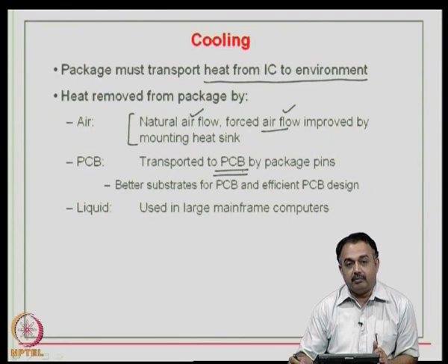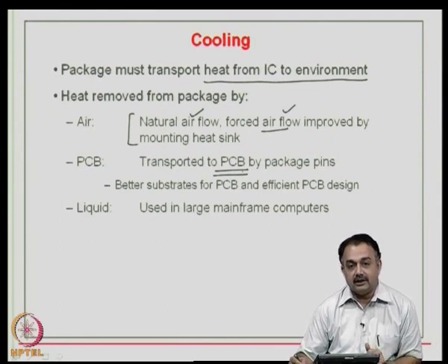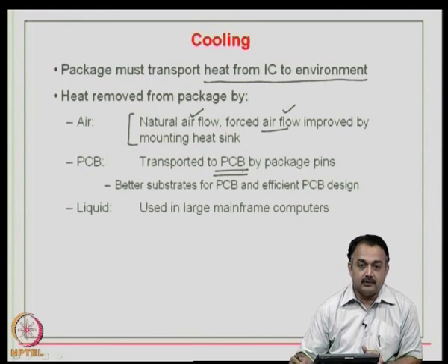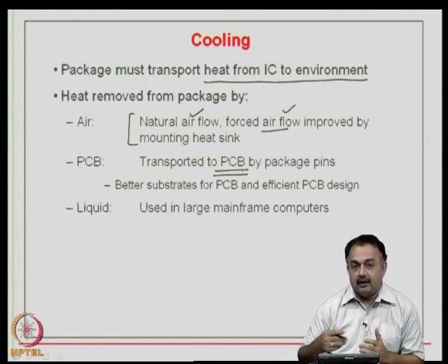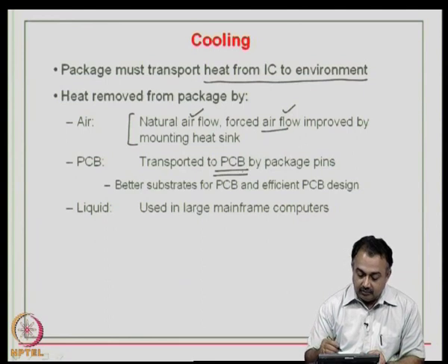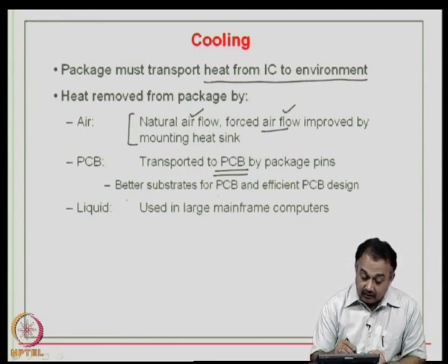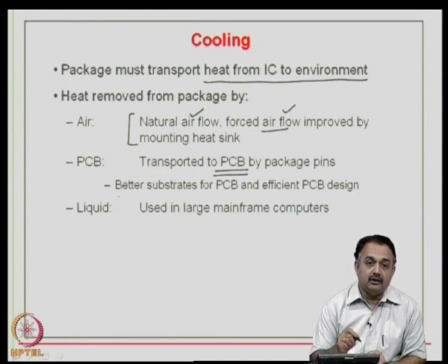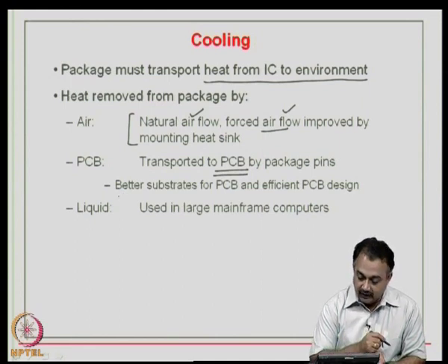Therefore, you must look at the printed wiring board not just as a rigid substrate or a flex substrate that is used for assembling your components. It should also be considered as a substrate that can take care of cooling, removing heat.